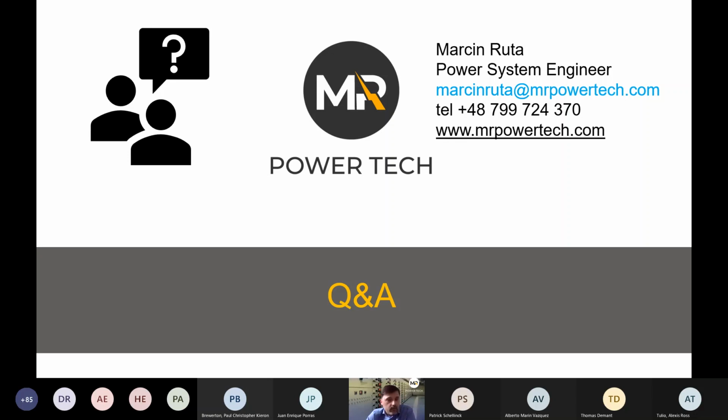And I would say, if your software allows you to use IEC 60909, stay with IEC 60909. Then you have all the equipment evaluation with the same value, all your protection aligned with the same value, and all your arc flash results aligned to the same value. Because if you use comprehensive and start to play with this, you will start to see the difference of current, and this difference might be big or small enough for you to see it in the arc flash results. So either you stick with IEC 60909 or you go with comprehensive. But if you are in Europe, you should follow IEC 60909.